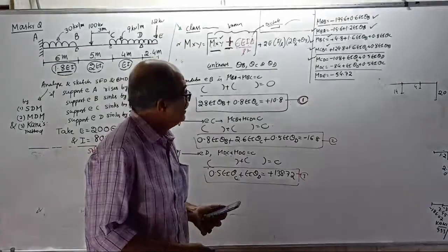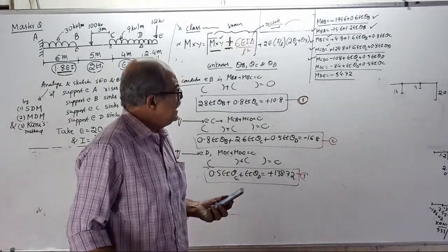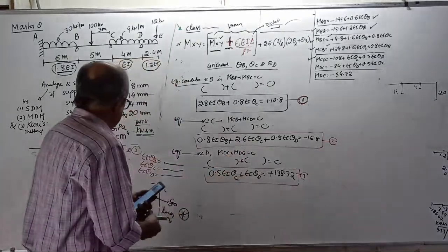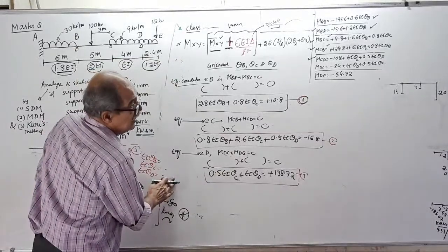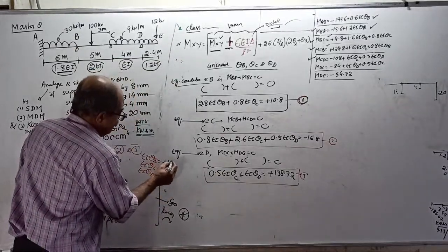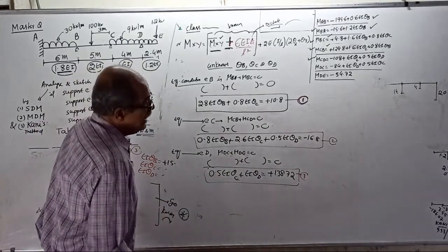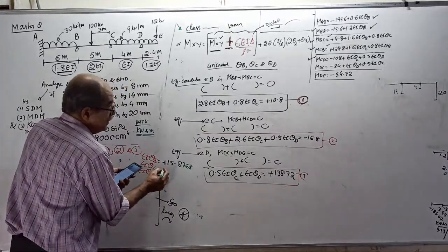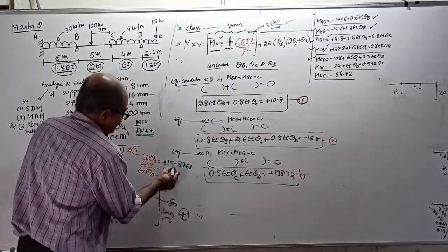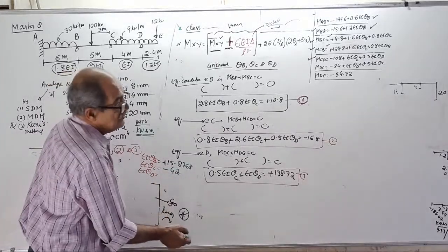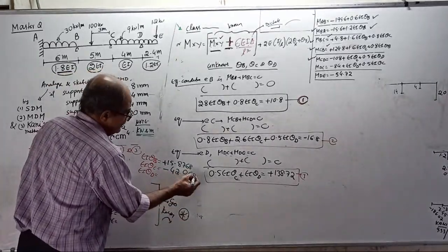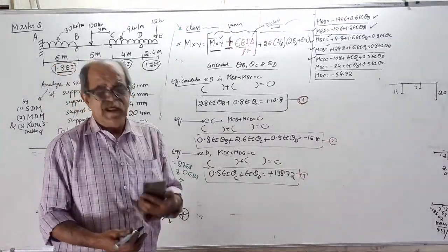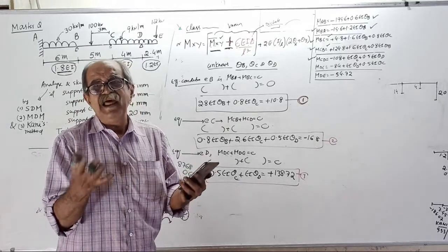35 point? My answer is 15.8768. EI theta B is plus 15.8768. EI theta C is minus 42.0687. EI theta D I do not know, because I got a trick of eliminating that one. Anyway, you check later. Agreed?